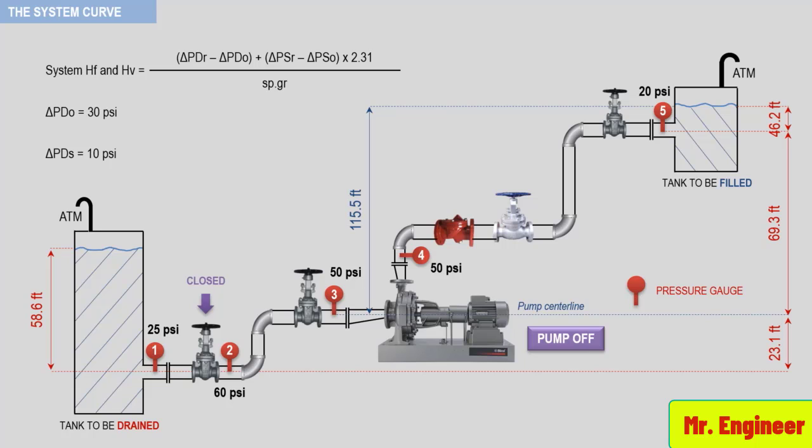Now open the gate valve between gauges 1 and 2. Start the pump and relieve the check valve if it is being mechanically held open. Permit the pump to run a few minutes to stabilize. We'll continue to note pressure gauge readings with the system functioning. Because all valves are now open, gauge 1 becomes our upstream gauge on the suction line. With the pump running, all activity on the suction side of the pump is separated from the activity on the discharge side of the pump.